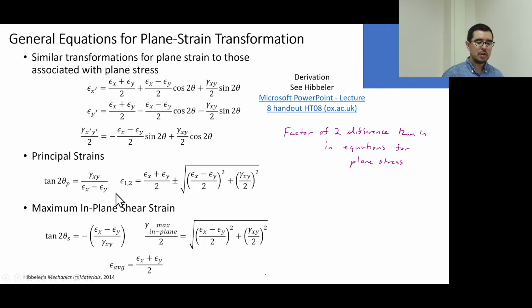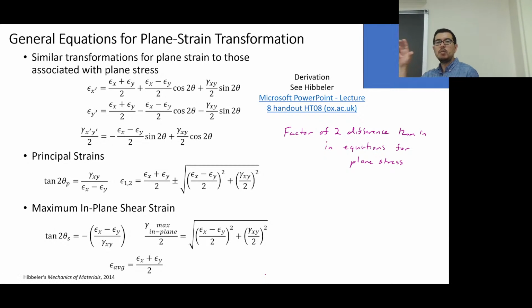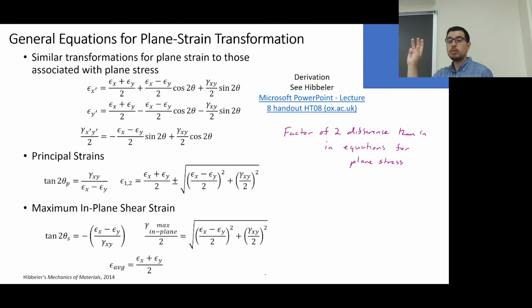If this were to figure out a principal stress, sigma 1, sigma 2, this would be the same, except we have sigma x plus sigma y over 2, right? That's the average. This would be the same. That's the square root of this component under here, right? That'd be sigma x minus sigma y, over 2, but this would be just a tau xy squared, right? We just did this a few minutes ago when you had that problem, number 6.